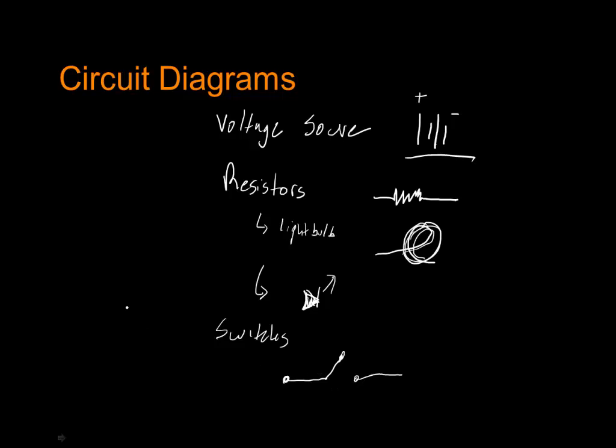Anytime you see wires that cross like this, that means this is a non-intersecting connection. So these 2 wires don't actually touch right there. They're just one overlying the other. If you see wires touch like this or with a dot, those wires do touch.